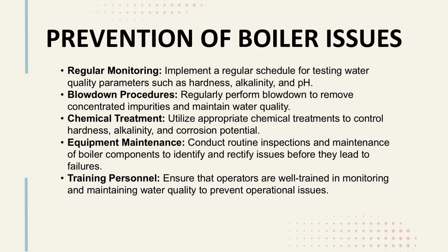Regular monitoring. It's important to continuously monitor key water quality parameters, including hardness, alkalinity, and pH levels, to ensure the water stays within the optimal range. Blowdown procedures. Regularly removing concentrated impurities through blowdown keeps the water clean and helps prevent buildup of solids. Chemical treatment. The use of appropriate chemicals, such as oxygen scavengers, phosphates, and anti-foaming agents, ensures that water remains free from harmful contaminants and is well-conditioned for use in the boiler.